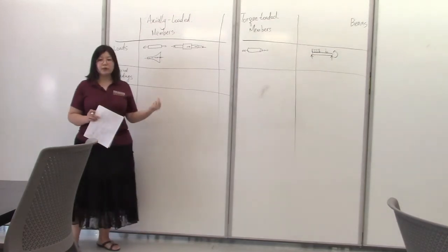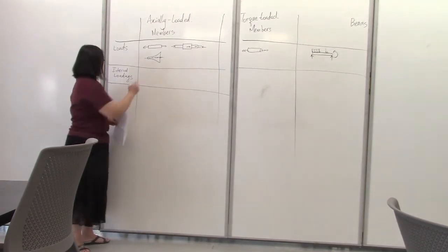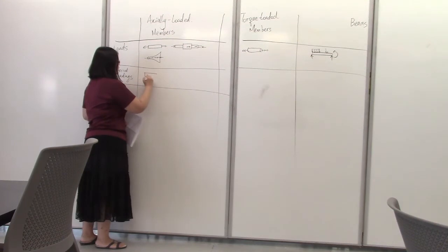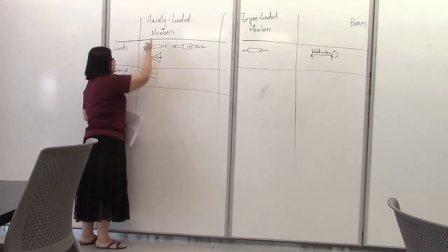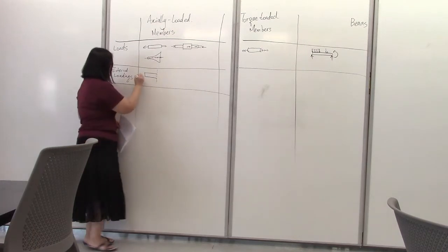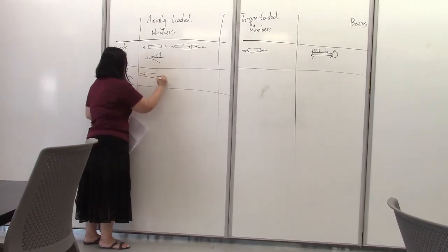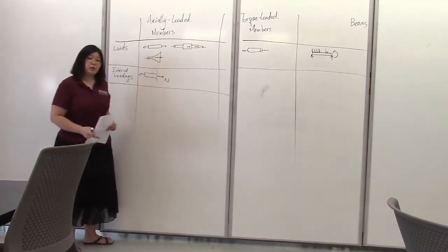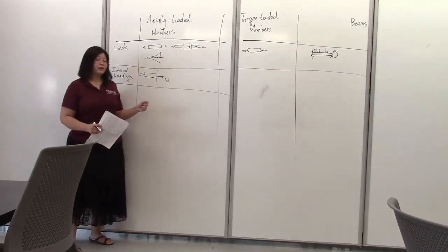Those are also referred to as the axial forces. So when you use method of sections, you could make a cut along a specific cross section of interest, and then you could look at the internal normal force. Now there is a sign convention.